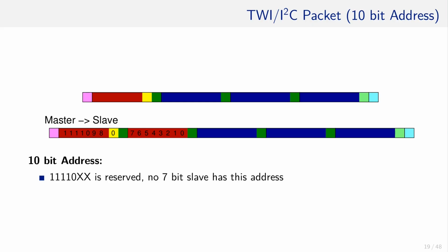These initial 5 bits do not count for the 10-bit address. 10-bit address slaves are aware of that and expect the address to follow those initial 5 bits, occupying 2 bytes in total, as shown in the figure below. If the master wants to transfer data to the slave and the direction bit is 0 as shown here, the remaining transfer remains the same.